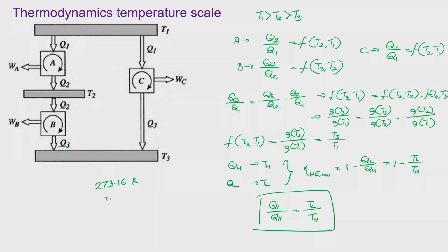You can say this absolute 0 is actually a proper point which is independent of any fluid properties, and therefore, that should not be mixed with the ice point or steam point. But this is also a perfect parameter, which is definitely the triple point of water, but it is again independent of temperatures and pressures. So, again, an absolute constant. The temperature scales which are defined based upon this particular principle are called thermodynamic temperature scales, or sometimes called the single point temperature scale, because we just need one reference point like this particular one here for Kelvin or Rankine scales. So, with this knowledge, let us move on to check out what are the different ways we